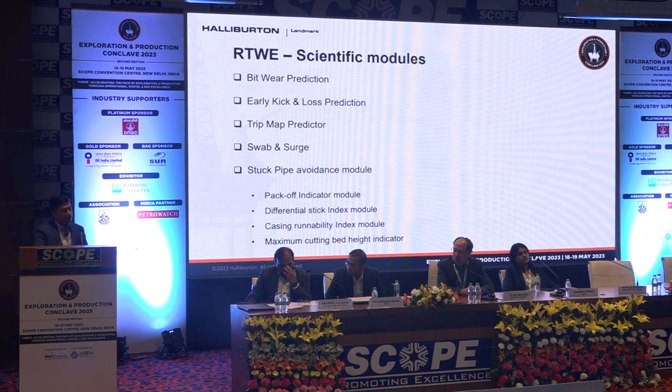When you start tripping out of hole, it gives indications at different depths or trajectory-wise positions of how the hole condition is, whether it is good, bad, severe, critical, or whether you have to stop there. So it predicts that condition. It's again a probabilistic model. It helps you take decisions, so you are not blind at that point. You have some data, you have the parameters which are the indicators for all those trips.